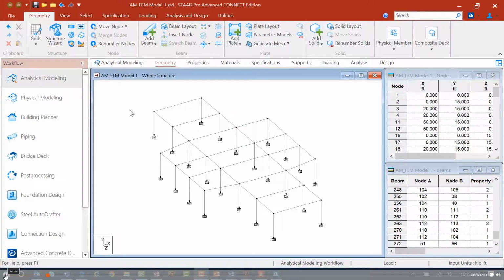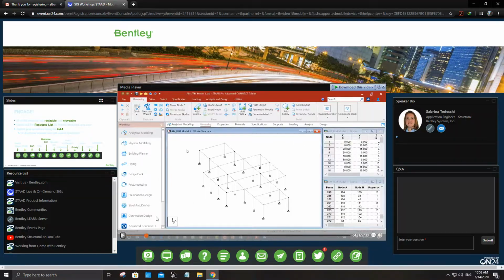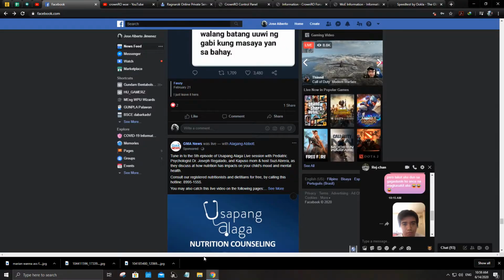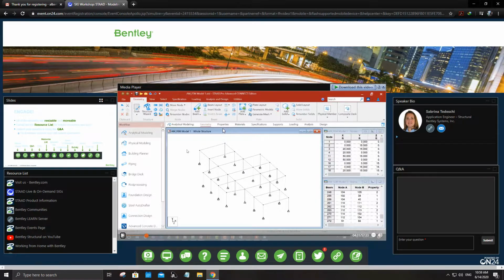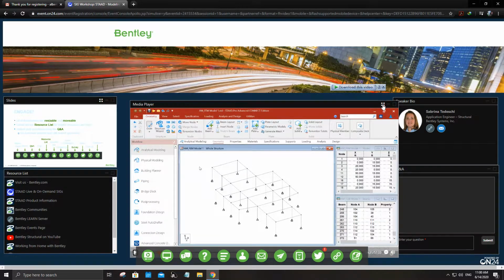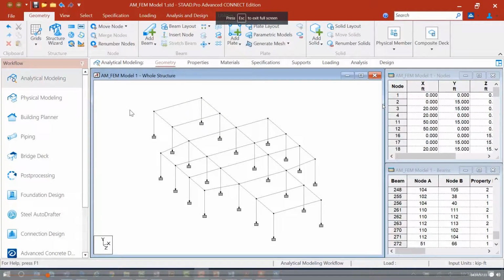Since there is a need to evaluate displacements at arbitrary points within a slab around the perimeter, slabs will be modeled using a mesh of plate elements in such a way that the nodes of some elements coordinate with the points of interest within our slab area.